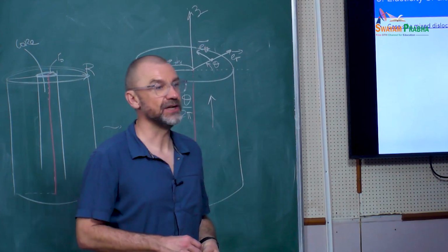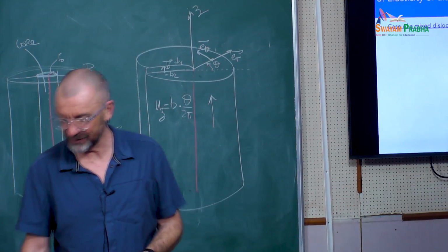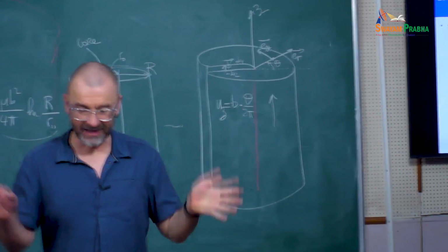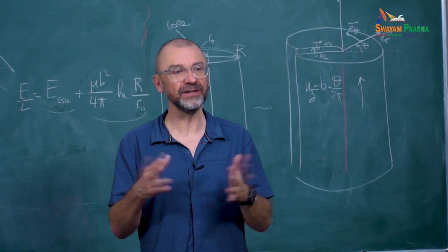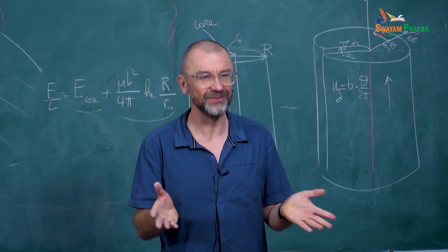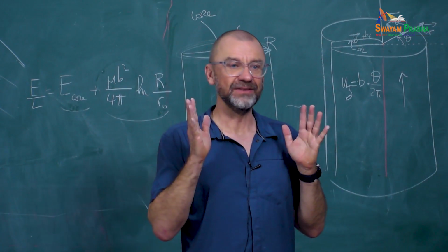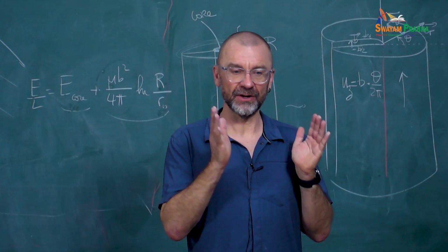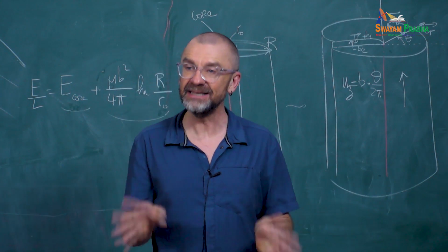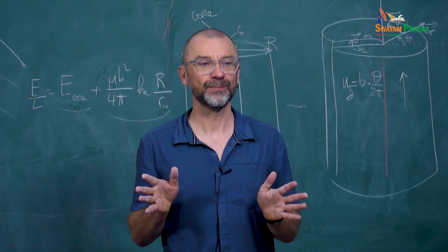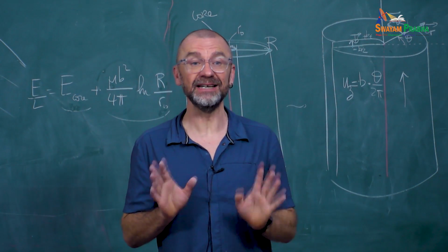Now, mixed dislocation. This has both a good thing and a bad thing. In every textbook, everybody talks about edge and screw dislocations, and so a lot of students think that there can only be edge and screw dislocations, which is the bad side of it. The good side is that once I know the energy and the stress fields of edge and screw dislocations, I know the displacement field and stress field of any dislocation because of the superposition theorem, because elasticity is linear.